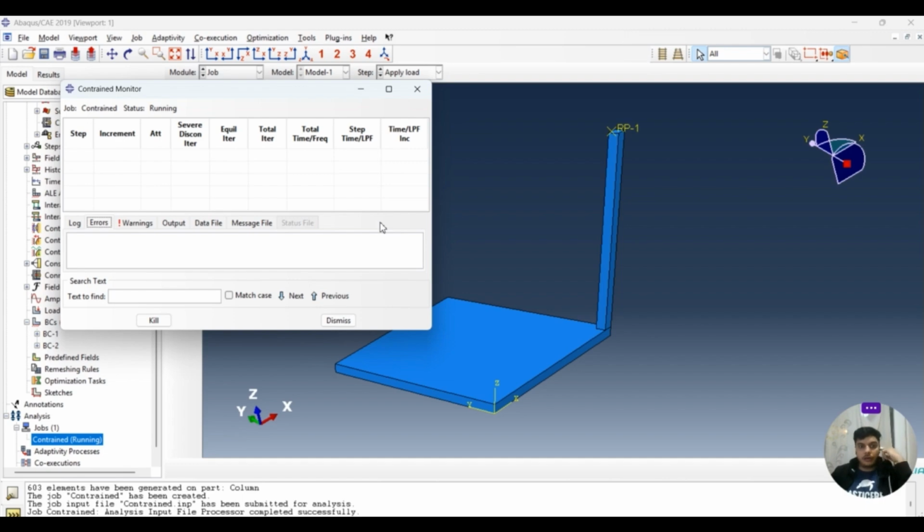Also, I hope you understand the concept of plasticity and adding two steps. Make sure that in steps you can add as many steps as you like. You can remove the load, you can apply the load. There's a cyclic way of understanding step behavior. This is really important for us from a broader perspective. For example, when we have fatigue analysis or cyclic loading, this is exactly where we can go ahead and define as many steps. So